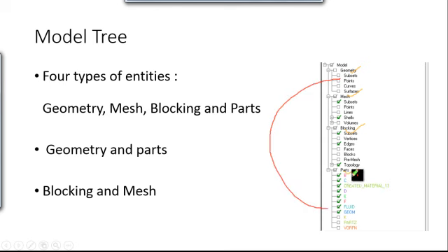So here I divided the different surfaces into different parts, like surface B, surface C, surface D, surface E, surface EF. But in a typical simulation, you will normally define them as the inlet, outlet, symmetry, wall, pressure inlet, velocity inlet, something like that. And then there comes a mesh, which is the result of the creation of mesh from the mesh menu, or conversion of pre-mesh as a blocking to the mesh.